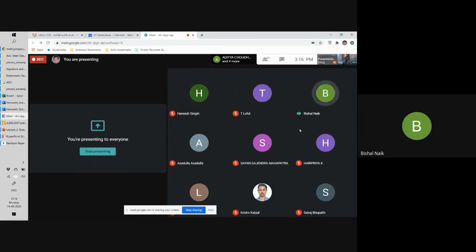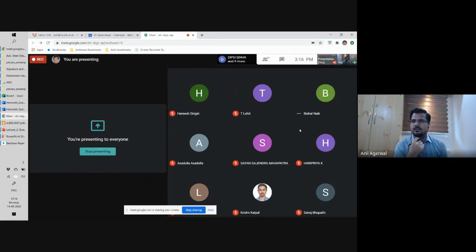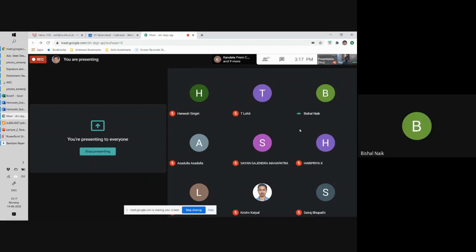No, sir, it's not like that. The net section won't fail by yielding, but will fail by rupture. That's a confusing sentence to me. Can you try to reword it? Not fail by yielding means what? Means the governing situation in net section will be rupture, not yielding.